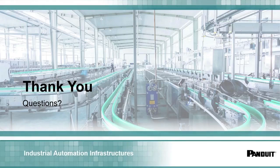In the control industry, we discovered that by putting the I/O closer to the machine elements, distributing that I/O, that shortened the amount of cabling we needed to use to get to the PLC. So we just have a short run going from the device to a cabinet with the remote I/O, and then we'd have one cable that connects the remote I/O back to the PLC. That saved us a lot of costs, it saved us a lot of real estate, and actually allowed us to scale and deploy much easier.